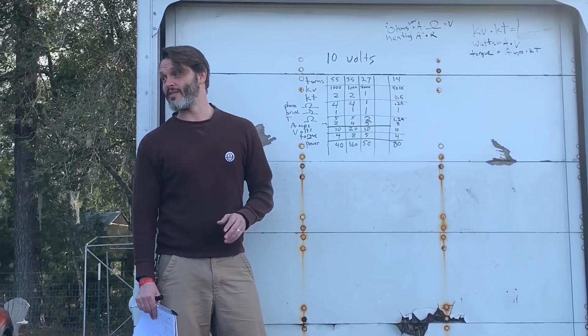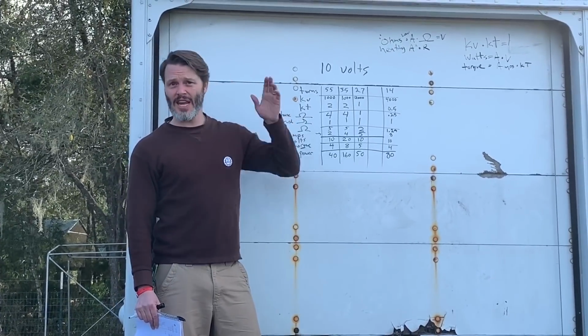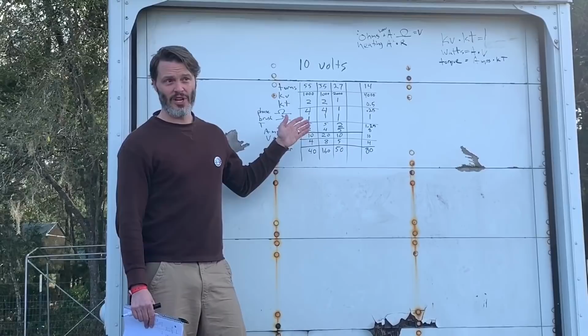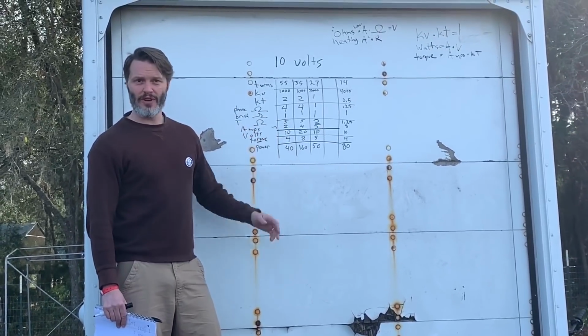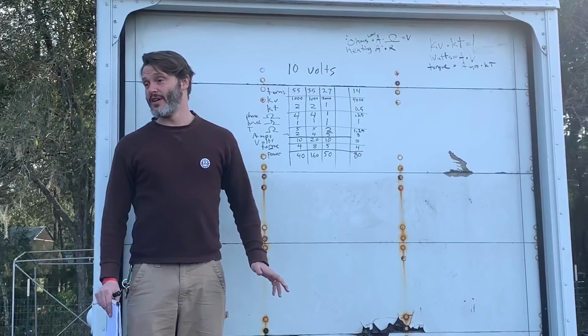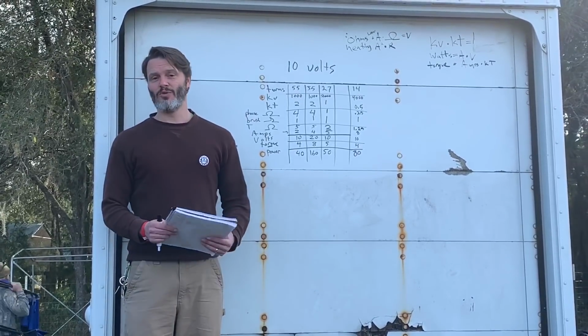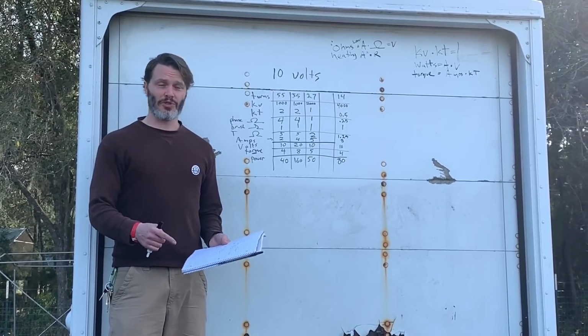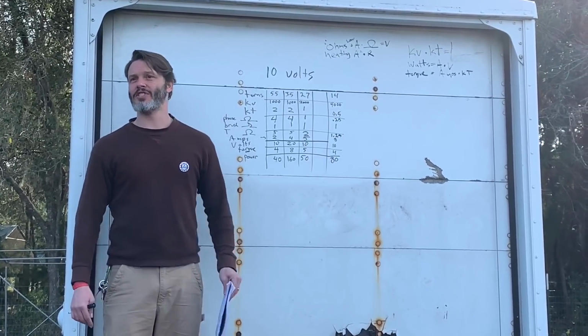Now, let's say you don't even need all that wheel speed. Maybe you don't want that high of a kV. A lot of people love 1,000 kV to 1,500 kV, like the 55 turn to 35 turn range. And in that case, if you don't feel that you're losing torque, if you don't need more, then that's all that you need. So really, you should select your system based on the wheel speed that you want, the voltage that you're going to run, and then of course the gear down of the system that you get.